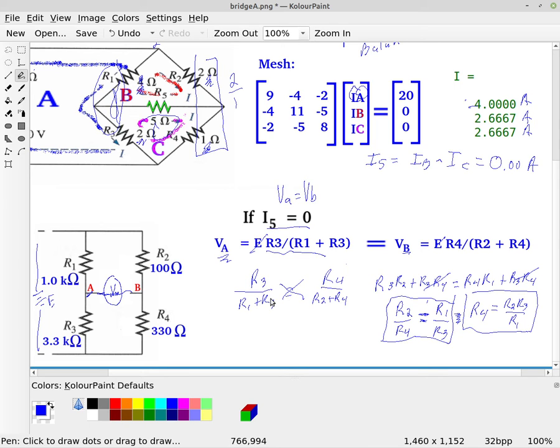And so when you look at this, then, like I say, if it's balanced, you can determine what the unknown resistance is. But if it's unbalanced, you can determine how far unbalanced that is. So this circuit is used greatly in sensors. So one of the most common sensors is a load cell, where we can measure force.